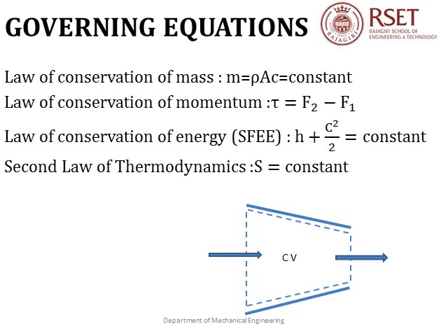In this case, we neglect the body force, and the viscous forces are negligible, so we are left with the pressure term and the reaction force that is developed because of variable area. Hence, our momentum equation reduces to the simplest form as shown in the second equation.